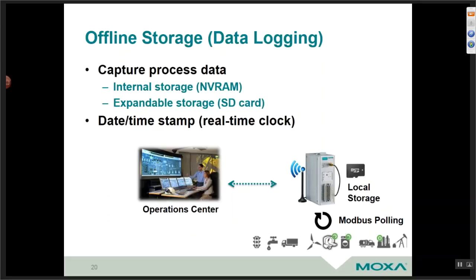Some of you might want to write programs to do this within some of the I/O equipment that goes in the cabinet. Think about whether you have to have a date timestamp on that. How can you capture the data if there's a momentary disruption, and then start pulling it back into your process after the fact? So it's great to think about that.